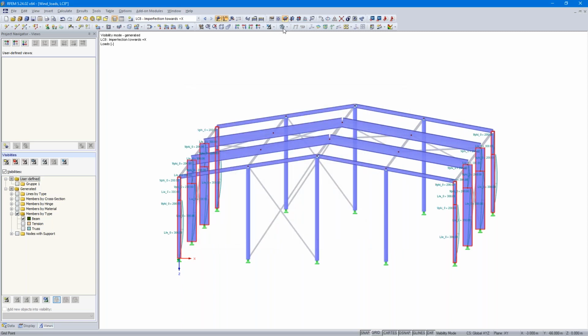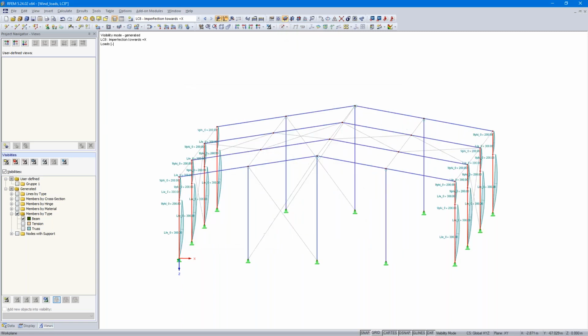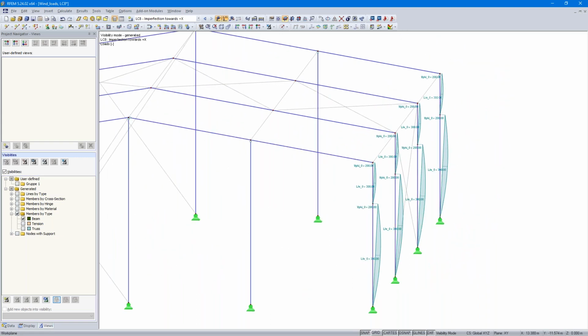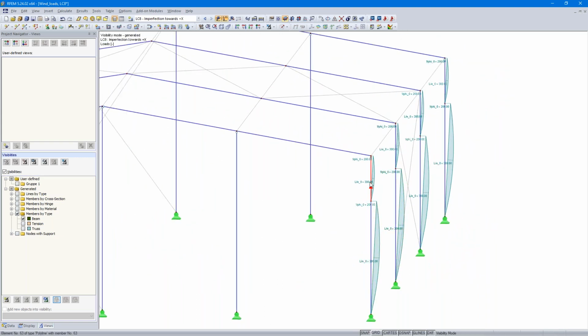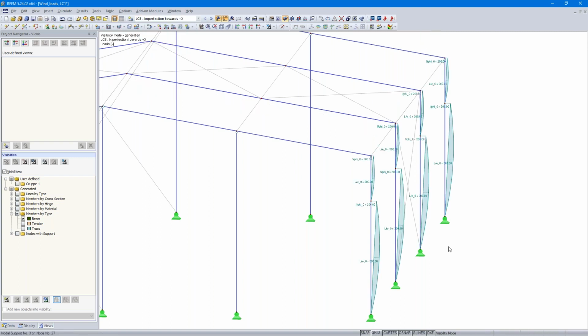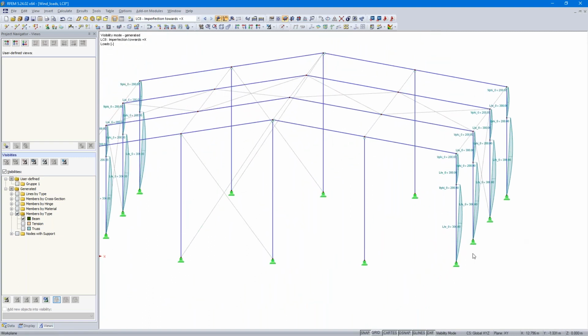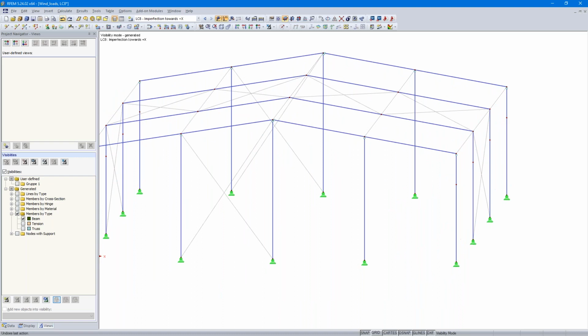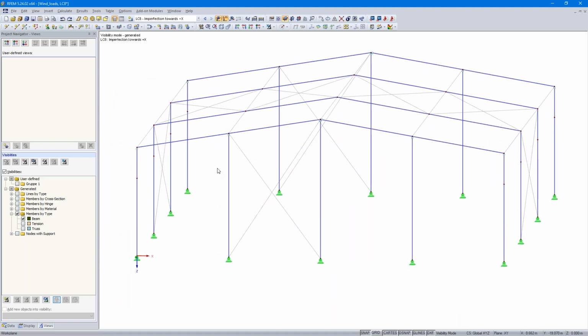So, and now I use the wireframe model. The imperfections are created but wrong, because the column is divided by a node because of the load in the load case number 1. Here's a load on the support from a console, etc. And therefore the member is divided. And that causes that the imperfection is wrong. How to create it correctly, I will show you.